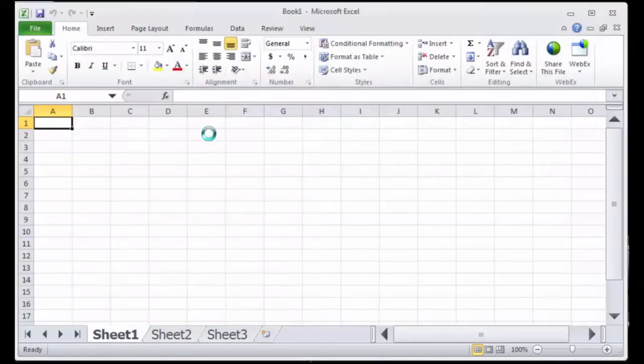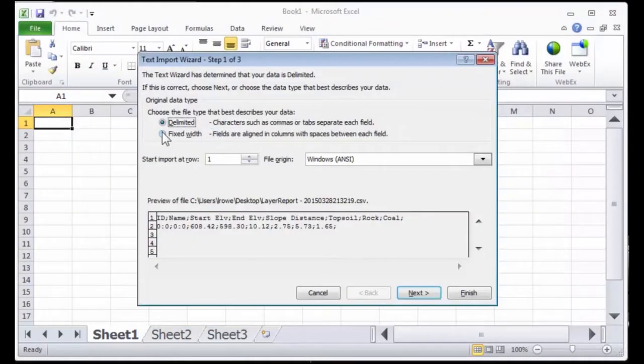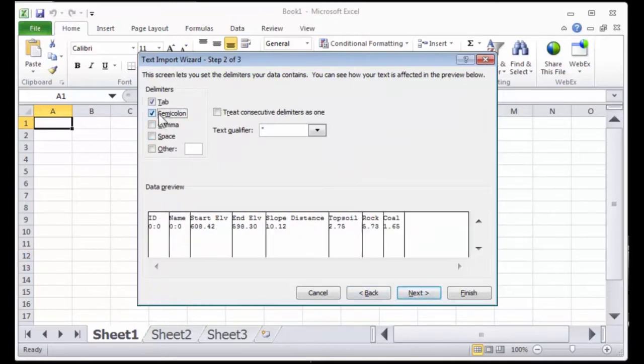Here it is. And now it's saying to create an importer. So it's not actually delimited by commas. You can see here that there's semicolons that are delimiting it. The reason we do this is because of countries that use commas as decimal points. So that can throw off the importer. So I'll hit next. Change it to semicolons for the delimiter.